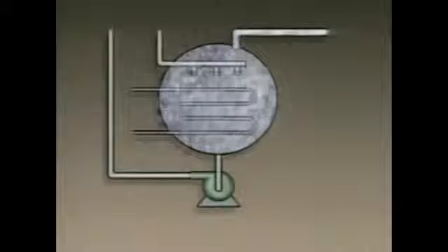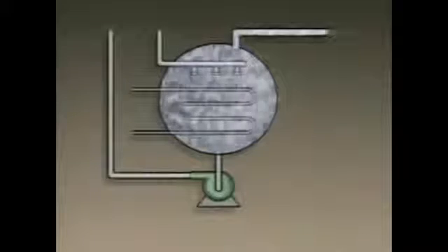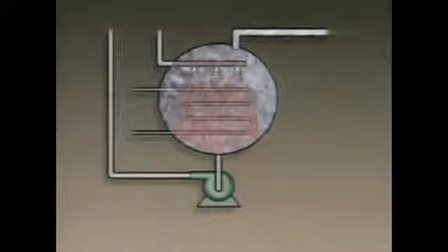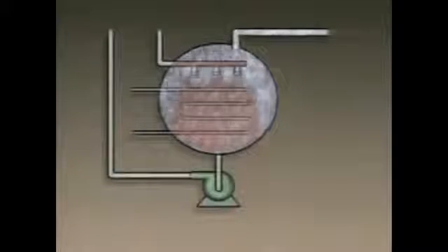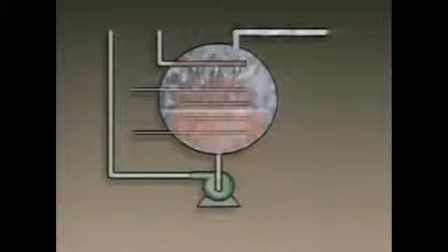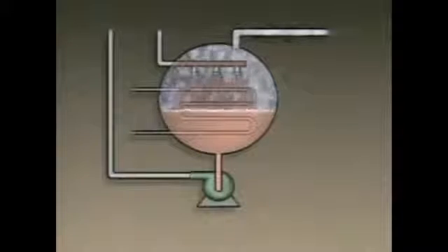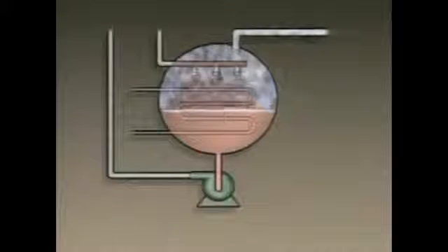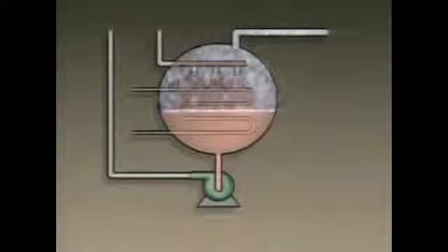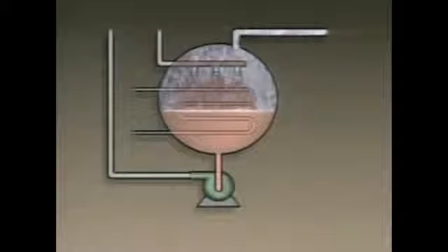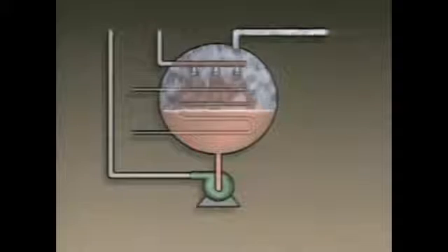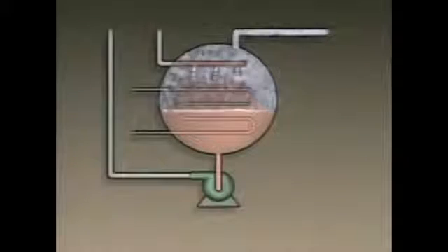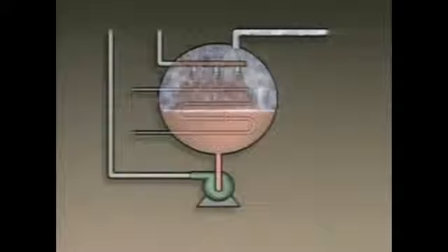The refrigerant vapor from the evaporator flows into the absorber section, where a relatively hot lithium bromide solution is sprayed into the vapor. The lithium bromide absorbs the vapor, and a mixture of absorbent and refrigerant is formed. When the lithium bromide absorbs the vapor, the volume of the vapor is greatly reduced, which causes the low pressure. The lithium bromide and the refrigerant will be reused in the system, but to do this, they must be separated.